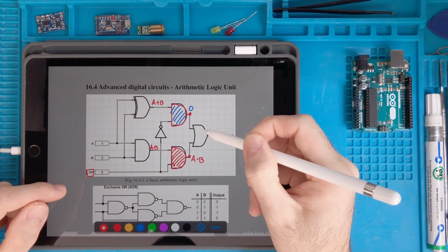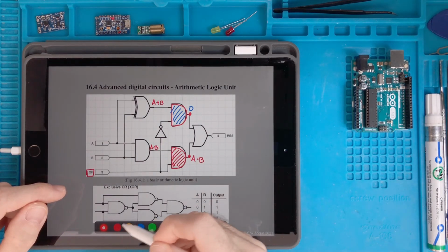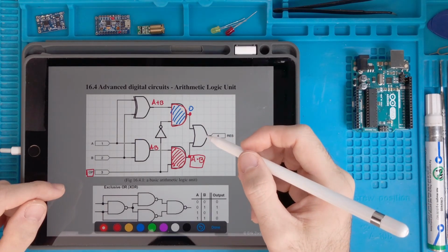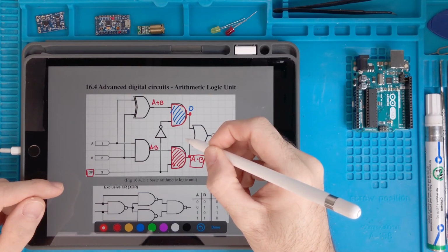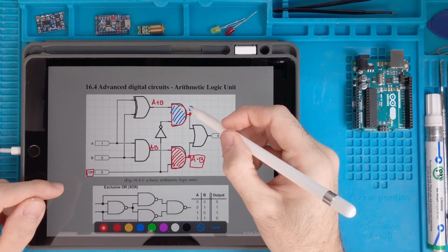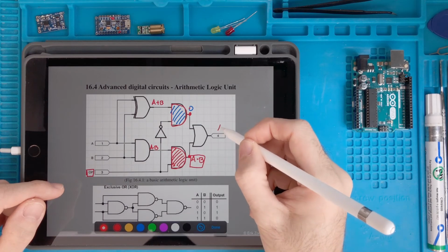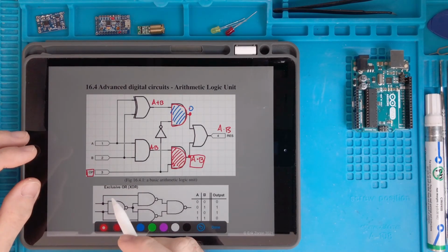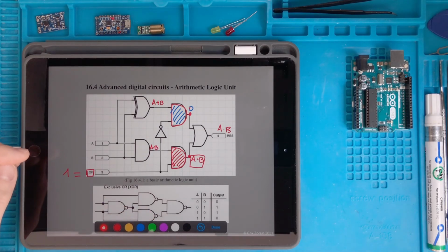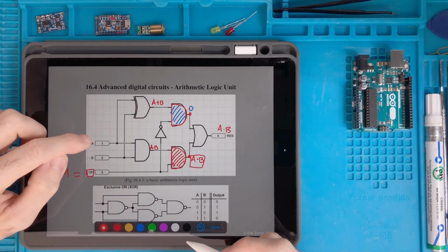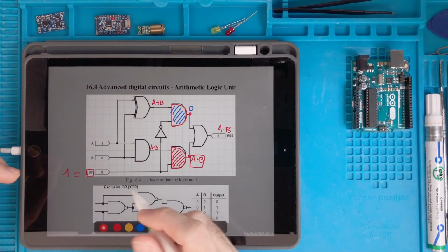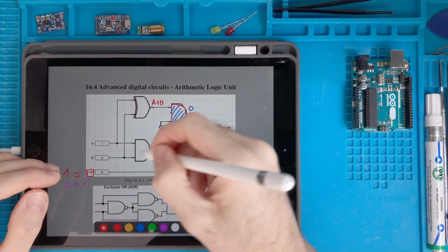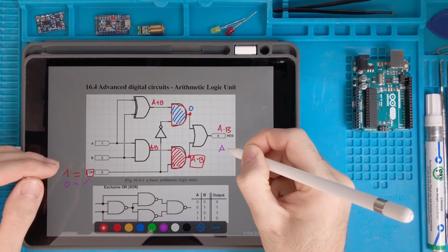Then, because here we have an OR gate, in this situation, when here we have the multiplication, we know that the truth table of the operation is that if this multiplication can be either 0 or 1, if here we have a 0, the result is whatever was present in this input, so it's a multiplied b. So here we have that when we set the operation input equal to 1, the output is the result of a multiplied b. Similarly, if we set the operation input equal to 0, then the result will be the opposite path, so a plus b.